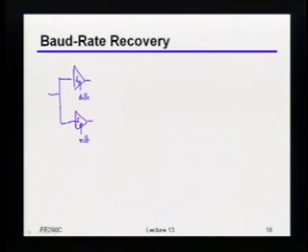So in other words, if the data was at 10 gigabits per second, then effectively we're sampling the data at 20 gigasamples per second, right? Because we have this comparator running at 10 gigasamples, but we've got another comparator also running at 10 gigasamples with a shifted clock edge. So, as you will see, that obviously has some power implications. It has some implications on how you build the phase interpolators and things like that.